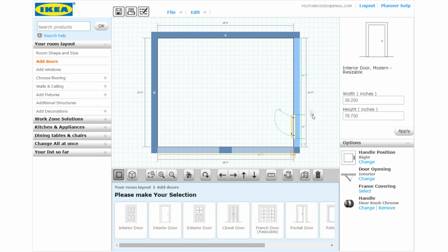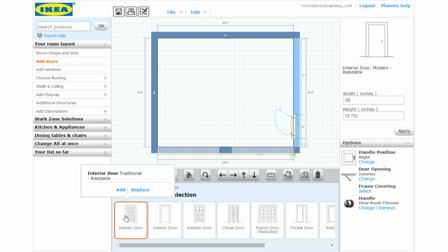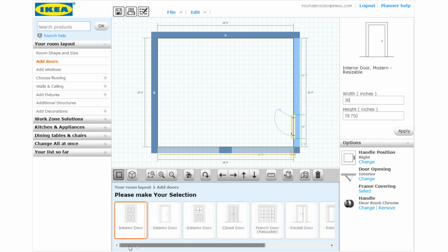So the windows or the doors, you can change the width of it over on the right. You select what you want to do on the left. You select what item, I guess, in the middle. Then on the right is where you do your final option for everything. So change the measurement and hit apply, and now the door's set. And you can change all this crazy stuff over here, but I'm not going to worry about that.